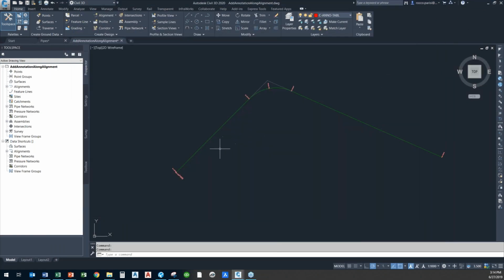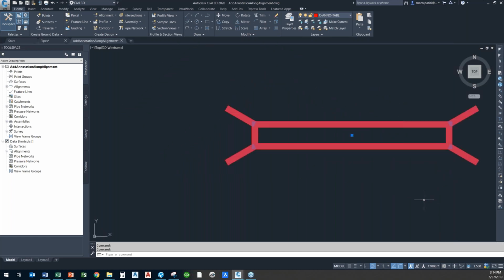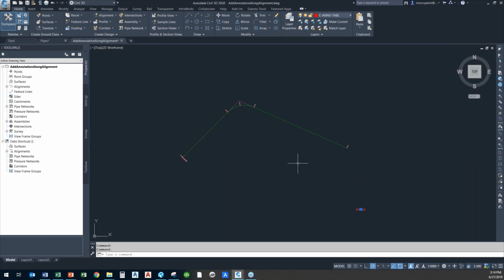And have it actually go in here and draw my bridge locations along my corridor. So then I can just run corridors from my road intersection to the bridge, and then pick up another segment from bridge to bridge and another one from bridge to end, okay? And you see that there is a block already built and defined in here for display purposes, right? And that's really all we need.